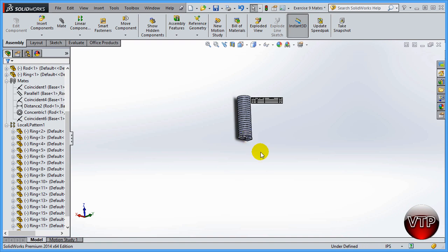So when you go into exploded view, it's really just to set up everything to print them out, or to set them up for a snapshot over here, and when you exit, everything goes back to normal. So when you change them, you're not really changing them in the assembly, you're just changing them in the exploded view.